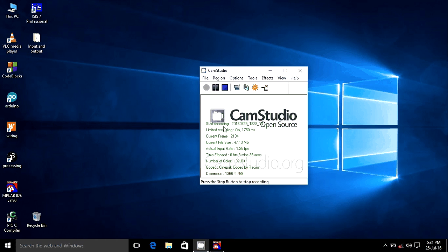If the room temperature is 100 degrees Celsius, the maximum, the sensor will provide 5 volts to the microcontroller. If the room temperature slowly increases from 0 to 100, the voltage level also slowly increases from 0 to 5 volts. This is called analog. It corresponds to temperature or anything, pressure or force.